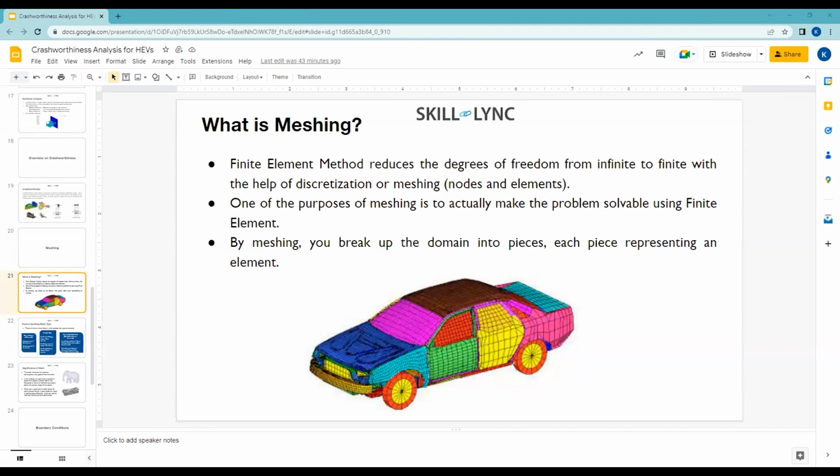In a 1D beam you have 2 points, the end points, here and here. So for this 1D 2-noded beam element, depending upon the points, you have a stiffness matrix. How exactly does that stiffness matrix for a 1D beam element vary? You have to derive that stiffness matrix.